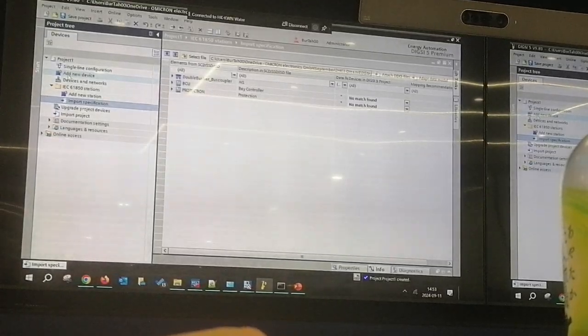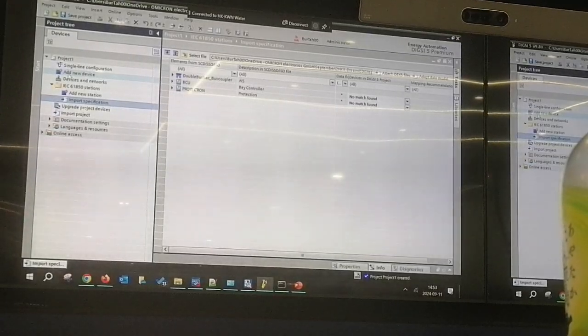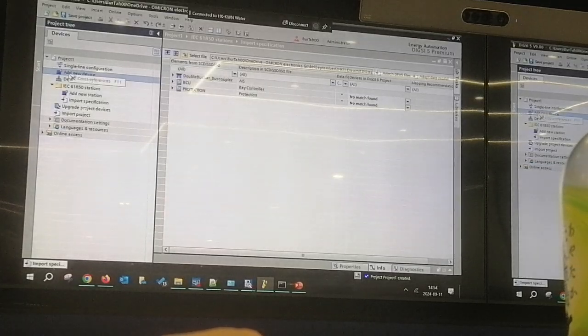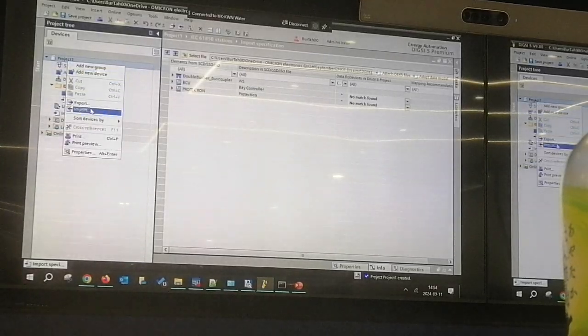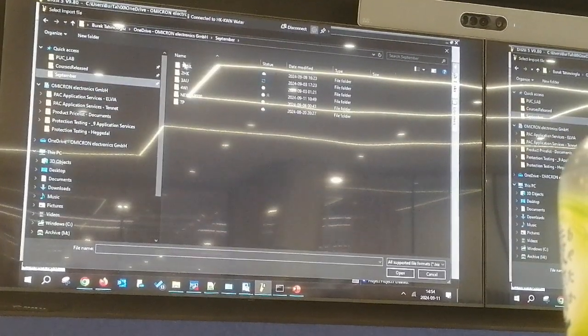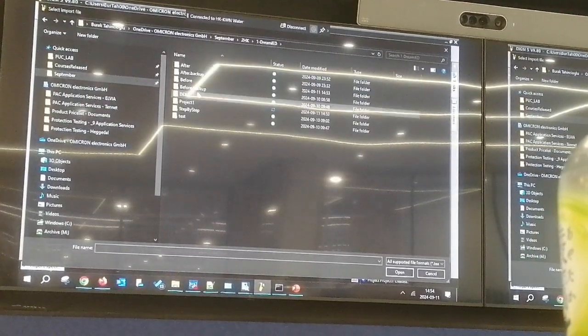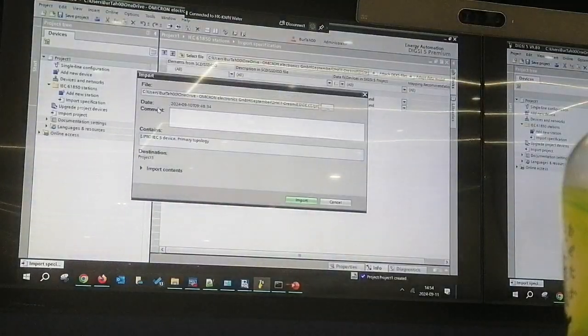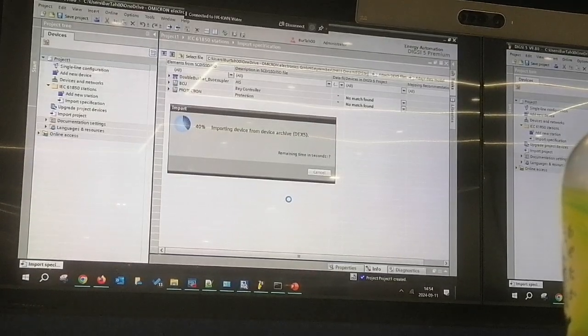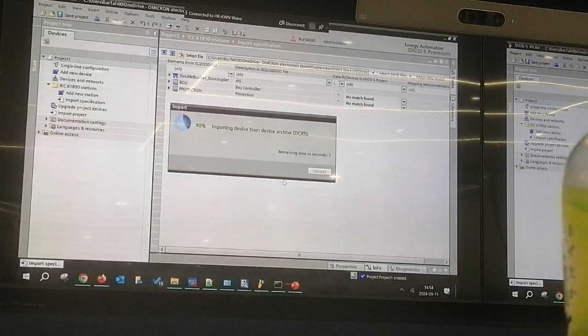Now I look to the shelves in our warehouse, what IEDs can be used. Look at this IED. I have the factory default file of this IED. I will add this device. Sorry, not add device, but import this device file. That I have, a text file. It's just the default file of a protection IED. Normally I don't have any transformer protection, but this is a transformer protection. But I have a line protection. No problem.